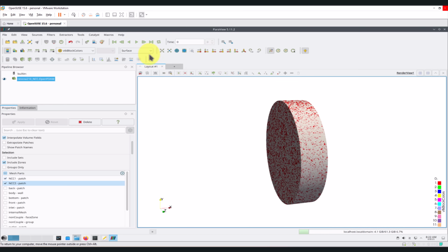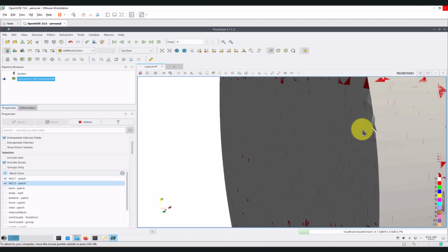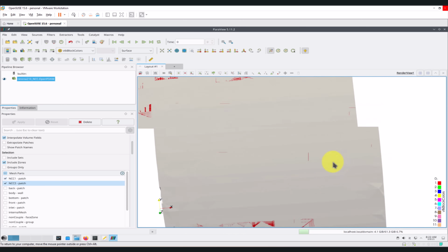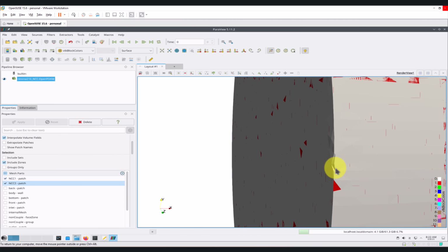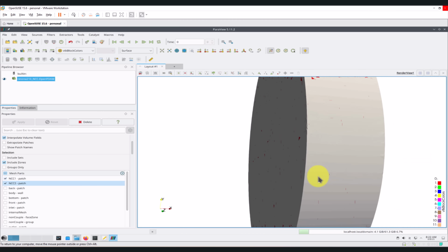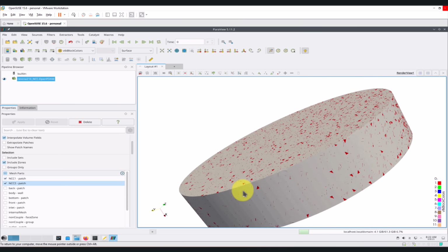Okay, and there you go. If you look closely, you have these issues here, in the edges of that region. Usually that mismatch that you will see is related to this. As you get a perfect mesh, it should be 1-1 or very close to 1.